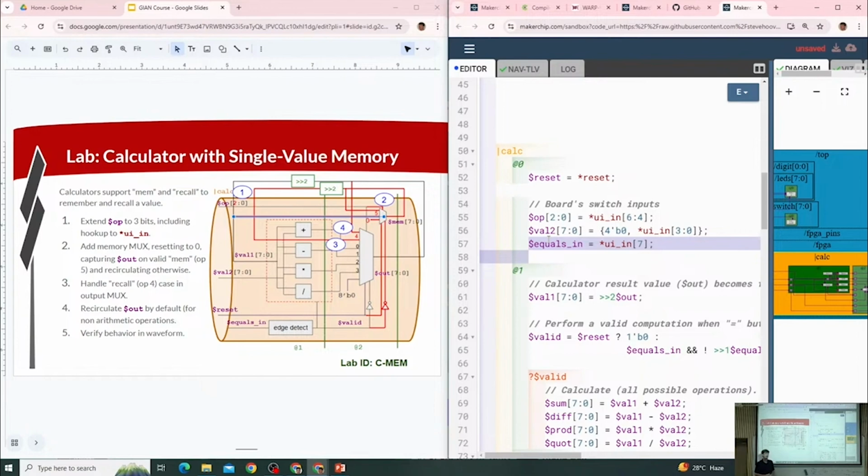I don't see any help with the scan for asynchronous. To me, asynchronous reset just causes mischief. It's not a question of synthesis, it's a question of methodology and how you code your logic. An asynchronous signal is going to propagate through the logic however it does and arrive where it arrives however it does. It's not necessarily arriving consistently.